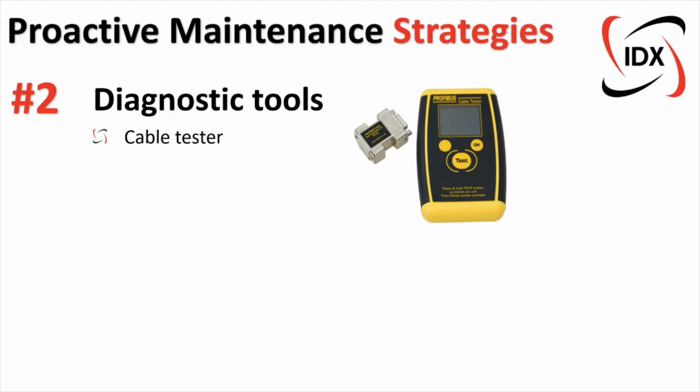A device like this shouldn't have too many steps or procedures. You see there's a nice big test button on this device. Simply plug it in once you've installed a wiring loop. In PROFIBUS you could often have 30 connectors on a single segment, and trust me, it's very easy to create a wiring fault or short when you're wiring up a long network, especially in hot, stressful environments. Very often on site, I've created wiring shorts completely by accident. As soon as I've connected a whole lot of cables together, I'll immediately check the cable, to make sure I've done everything correctly before connecting it into the devices.